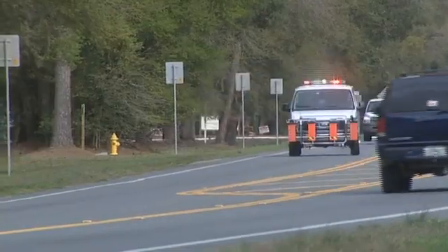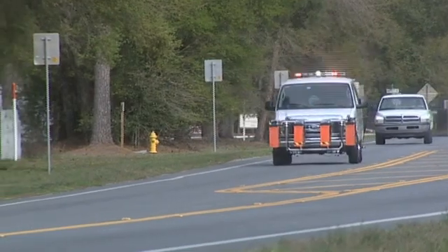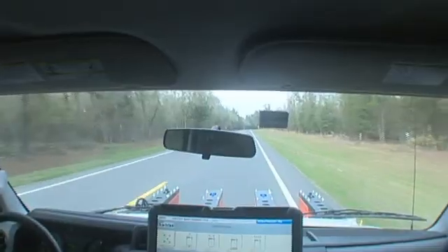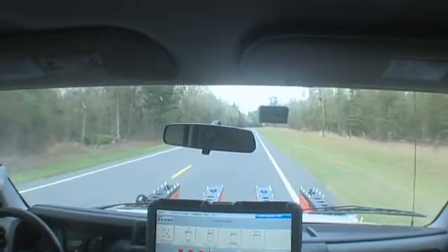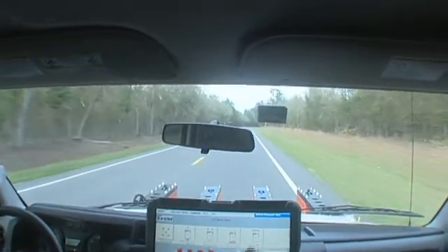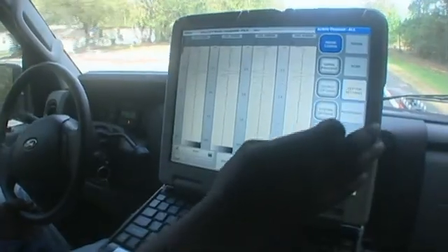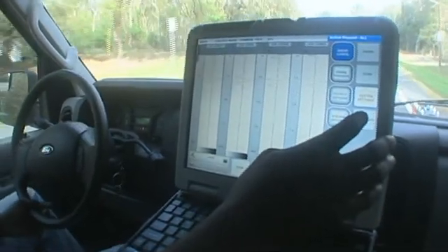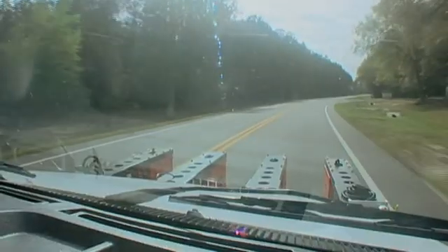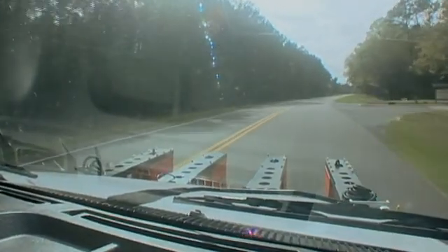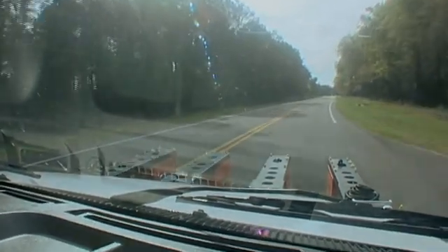The advantage of the radar van is that you can collect the density information much more rapidly and also cover the entire mat of the pavement surface instead of just those selected core locations.